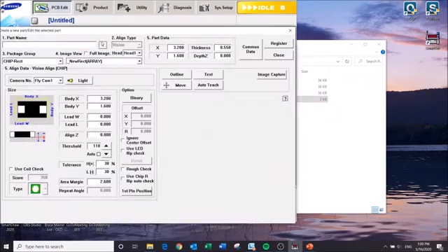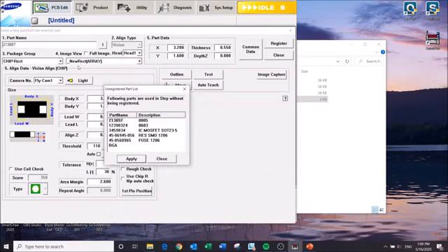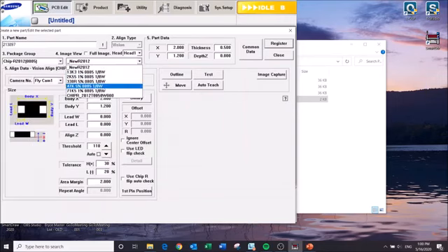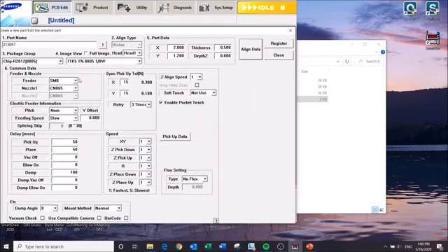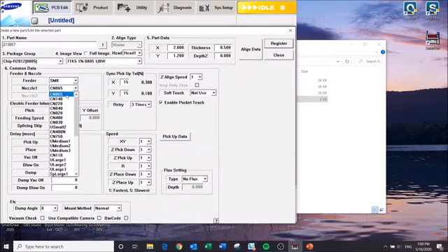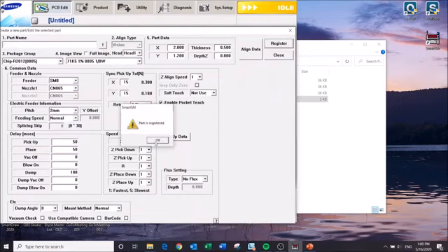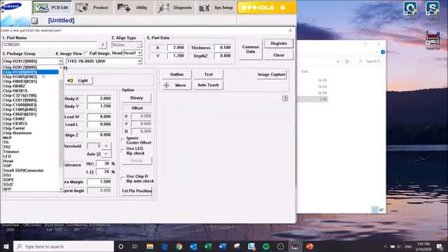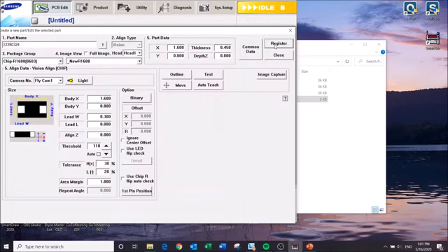Based on description, we will take known part numbers of the same package type, apply those to the part name, and make any modifications we need to. Here we're setting up our feeder size, nozzle size, pitch information, speeds and delays, and we just repeat that process for the rest of the components here. Again, we're pulling a component from our known library, and we're registering those parts.